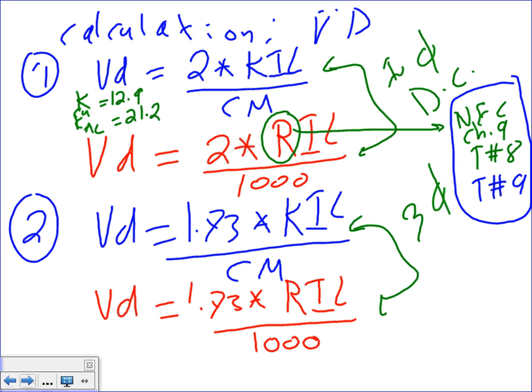In table 8, the resistances of my copper based on the size of the copper are always different, so how can you use a constant? Different for different conductors though. It's copper all the way down. Yeah, but different size. Right, but copper is copper, right? Yeah. So how can we use the constant in the upper? Here, because the amps, for example, using number 4 aught versus number 1, the amps will be different. Got it. So that's where it equals each other out. Good point though. All right, let's go to the 3-phase.